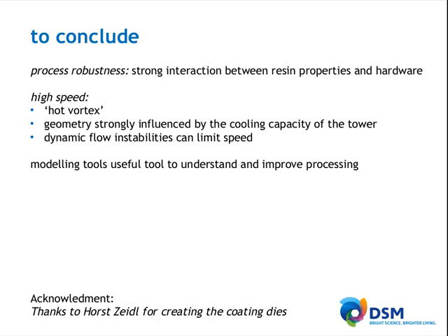Next question. Have you confirmed such high temperatures in the vortex? Well, it's very difficult to confirm that in practice. This comes out of theoretical analysis together with the rheological analysis of the resins. We know that there is a certain amount of viscous dissipation, so energy absorbance inside the resins. How much that really is remains an open question, but we're quite sure that it's actually quite severe.